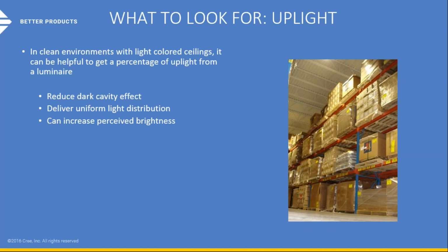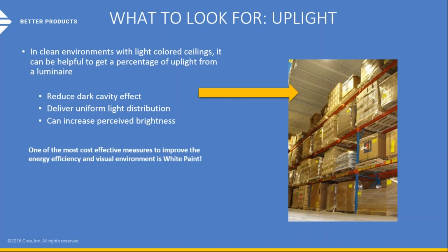To address some of that, some of the products that you would be dealing with in the LED world have the opportunity of reflecting light upward. They'll use special reflectors that have clear spaces on the top to give you some uplight to reduce the amount of cavity or dark illumination occurring at the very top. So, lesson learned here is your lighting designer and the overall environmental control person, as well as the facility managers, should consider all those as factors when looking at light selection going forward.